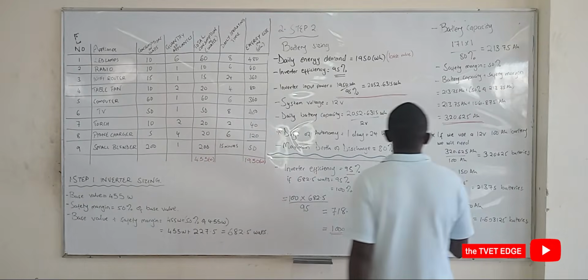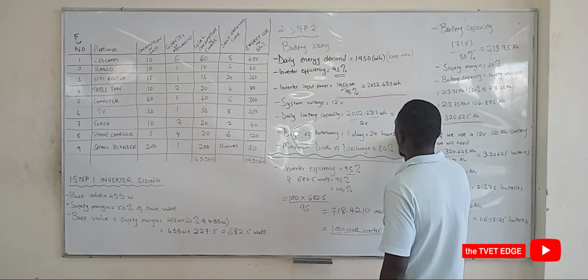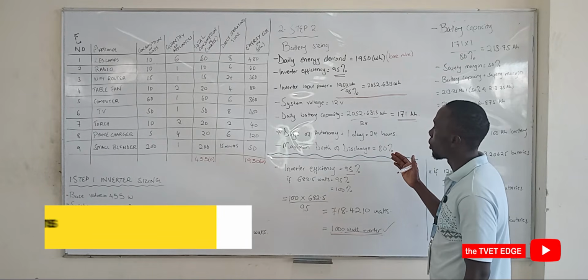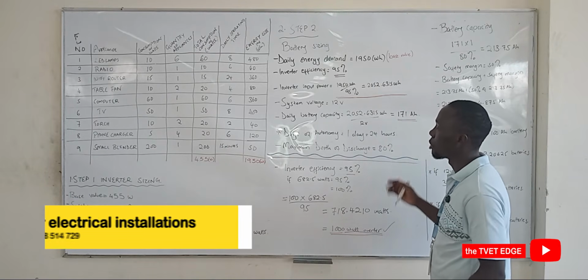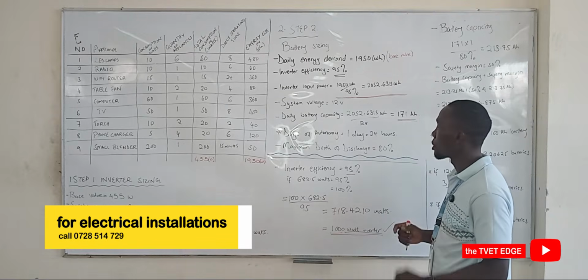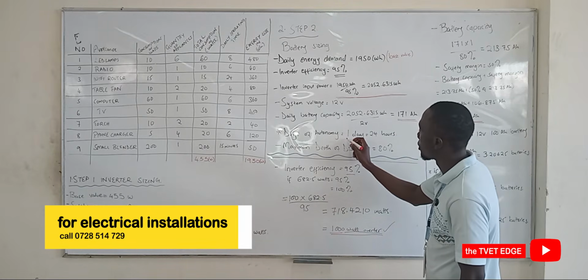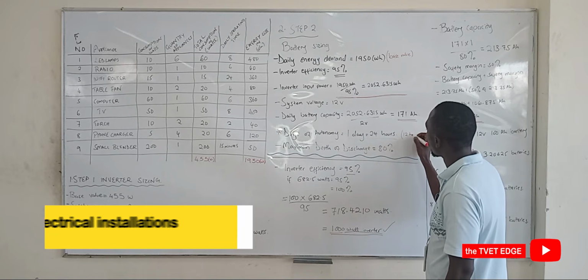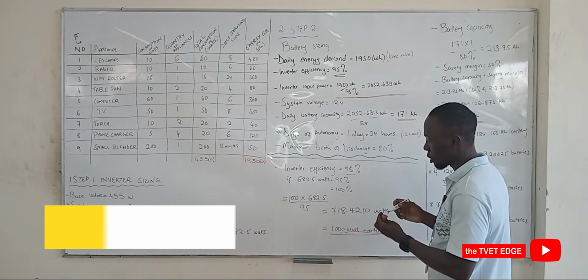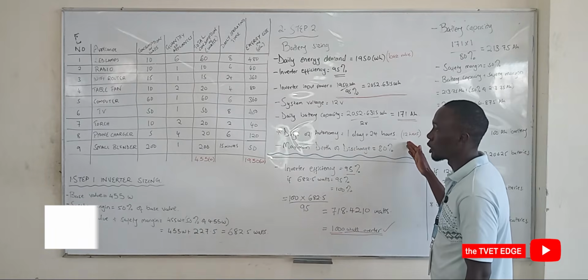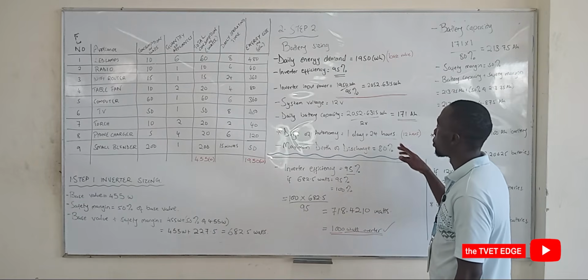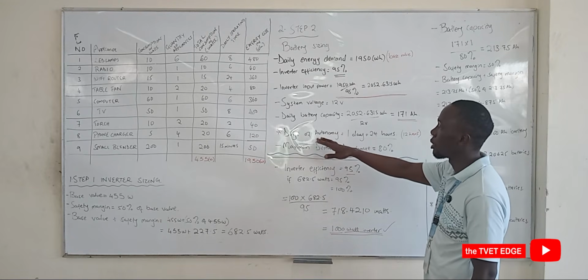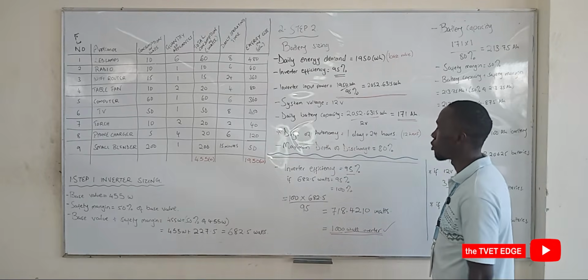But even then, I will still encourage you, if you are really looking into sizing a system based on this client's very specific demands, you can also calculate this to as little as 12 hours. That is equivalent to 6 p.m. to 6 a.m. So for now, let's calculate with 1 day, 24 hours, which is the most ideal value when calculating the days of autonomy.